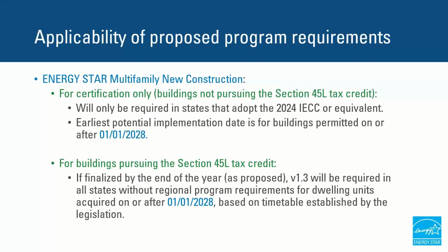Yeah. Okay, so let's start off with the Energy Star reference design. That's defining the Energy Star ERI target that you have to meet. The only change we've made there is that within the reference design that we're proposing for version 3.3, we have changed the airflow grade from 2 to 1. It's a little bit better. That means the ERI target is a little bit more stringent. Doesn't mean you have to use HVAC grading. Doesn't mean you have to hit grade 1 for the home to be certified. It's just setting a slightly more stringent target for homes to strive for certification.